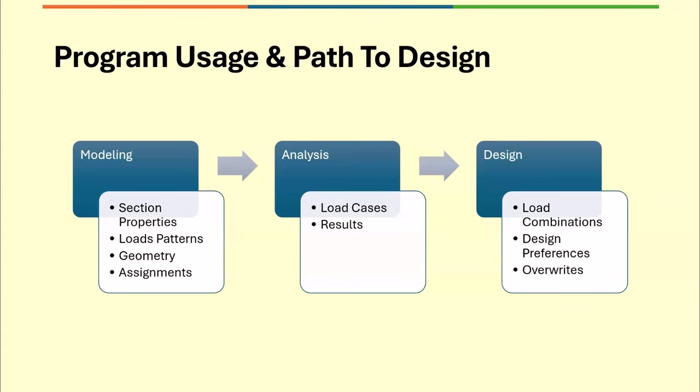Program usage and path to the design is very typical to the ETABS program, which we are conversant with. So the modeling involves definitions of material properties, section properties, load pattern definitions, spring definitions, and creation of the model, the geometry, and assignments of loads and other property-related assignments to those geometries.